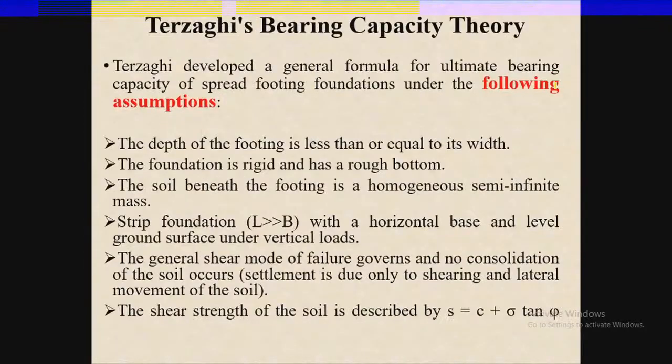Now let us discuss some more assumptions which were made by Terzaghi while deriving his equation of the bearing capacity. He assumed that the depth of the footing is less than or equal to its width, which means that the foundation is shallow.